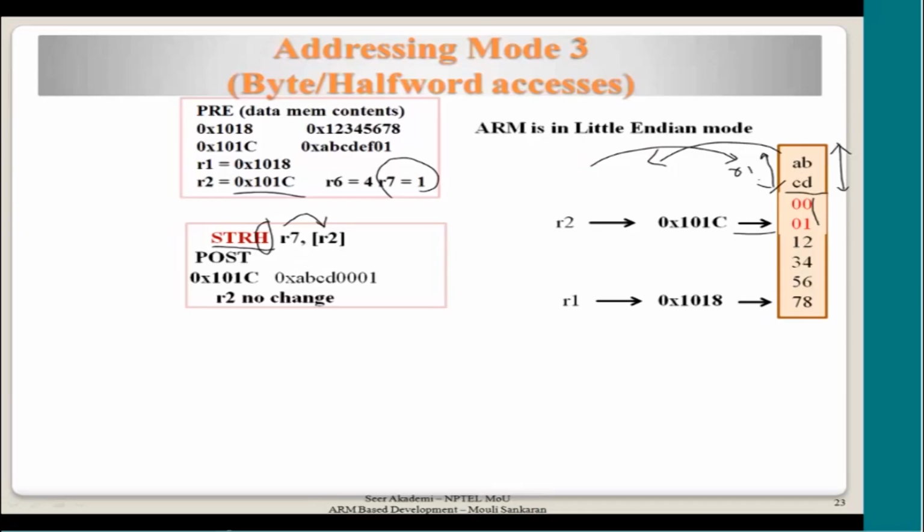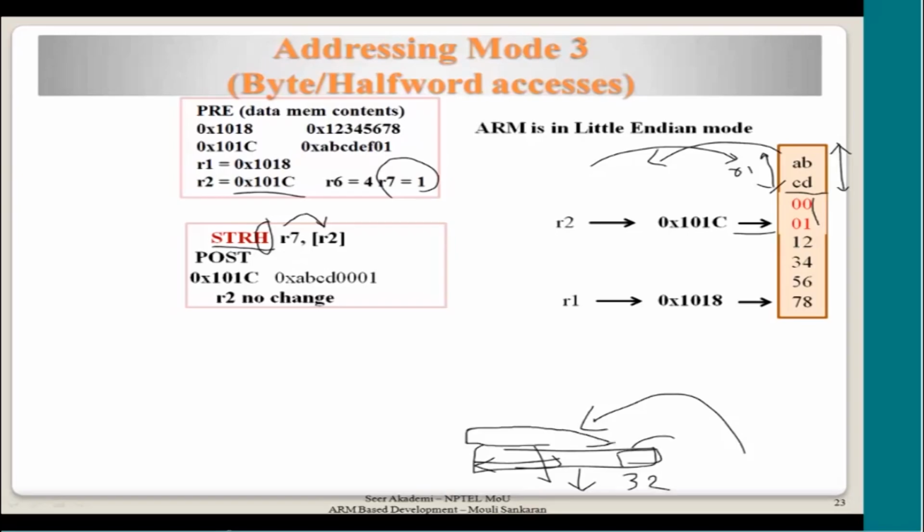So whenever you are doing a store, it doesn't impact the adjacent bytes or words in the memory. Only when you are loading from the memory, the register's adjacent bits are to be modified, because later on the program is going to be consuming this value as a 32-bit value. So if you have copied only 1 byte, you should tell the processor what to do with the remaining bits in the register. But that is not the case when you are writing into the memory.